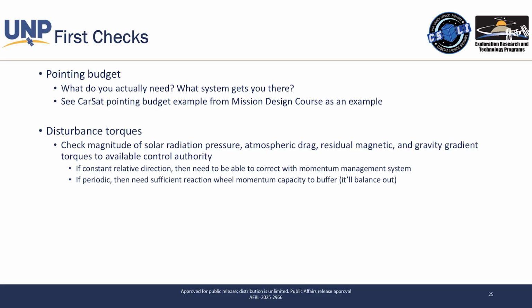We also have a lot of disturbance torques in orbit. So solar radiation pressure, like literally the sun is outputting particles and matter, well, that will hit your spacecraft and literally try to push you around. It's a very low overall force. And so when you're below about 800 kilometers in altitude, so low Earth orbit, atmospheric drag, the next thing we mentioned, really dominates, right? The atmosphere, even though it's very thin, still is your driving torque in orbit. Once you get above about 800, 900 kilometers, solar radiation pressure starts to take over. And that is actually the key driver out at like geosynchronous orbits and beyond.